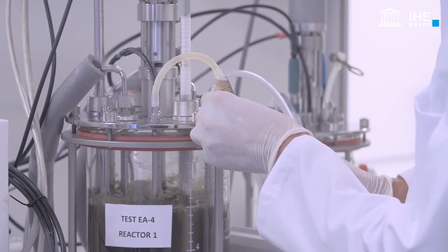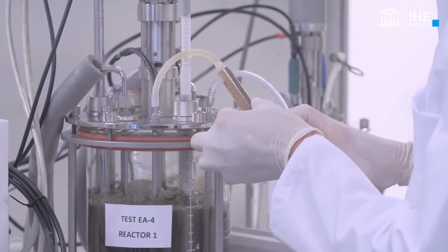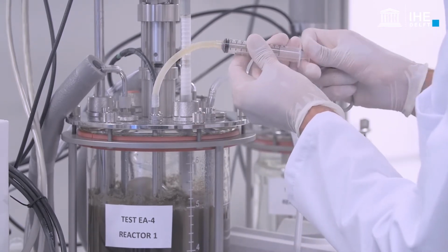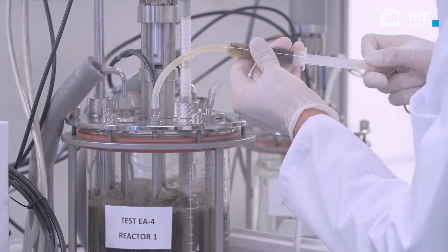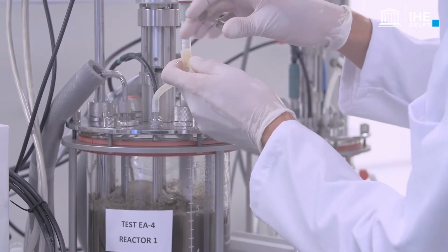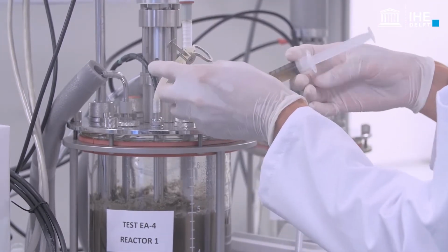Follow the sample procedure previously applied for filtered samples. This example only illustrates the collection of filtered samples. If samples for the determination of solids or particulate compounds need to be also collected, then a longer time interval is needed to collect and prepare all the samples in time.